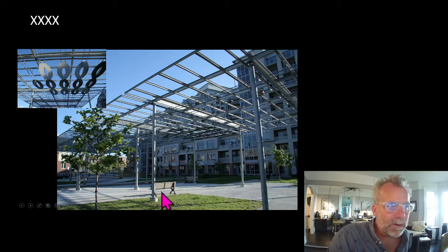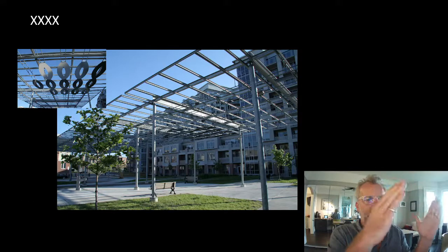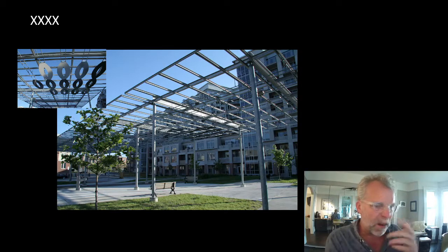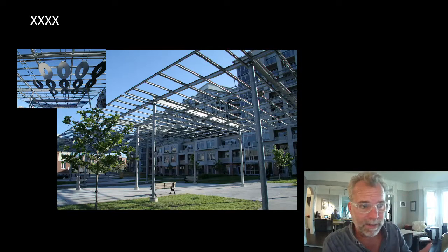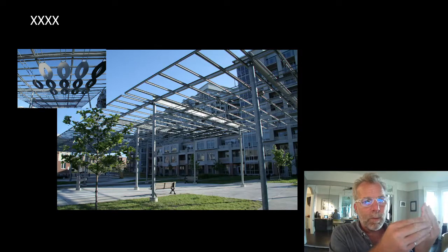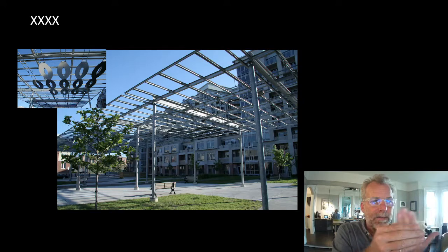This is one of the first projects where the code recommends a limit of H/500 lateral drift, and it doesn't qualify that. That's just the recommendation in the code. And we would have designed everything to that. But I dug into it at one point to find out where that came from, and it turns out it comes from windows in their frames.